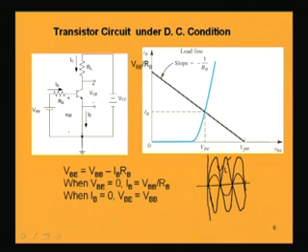How is this signal coming out of phase? One hint we have got just now, that it is negative with respect to the collector current, and collector current is again in phase with the base current. So, basically the output voltage will be out of phase with the input voltage, but nowhere during this amplification should the shapes change.